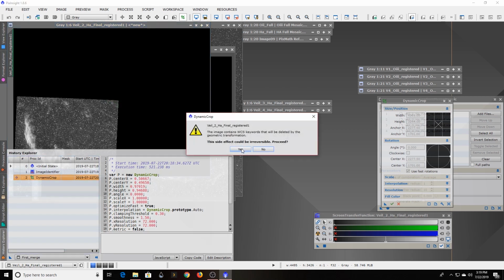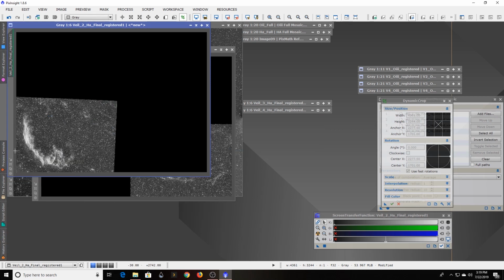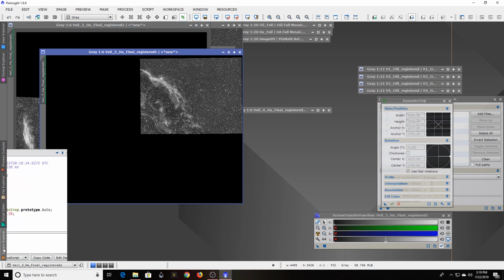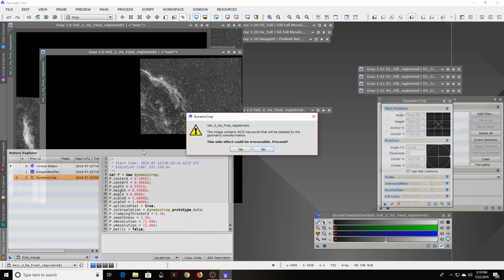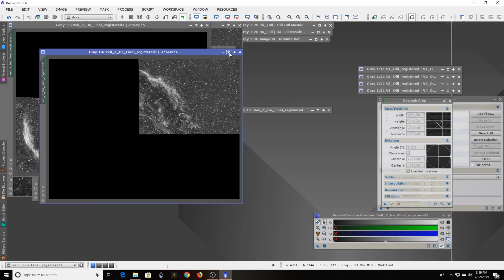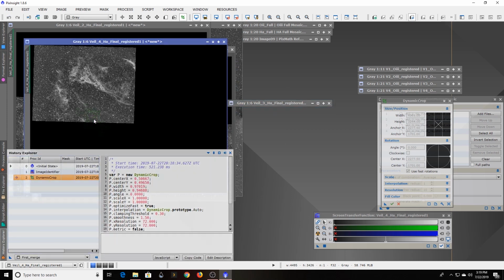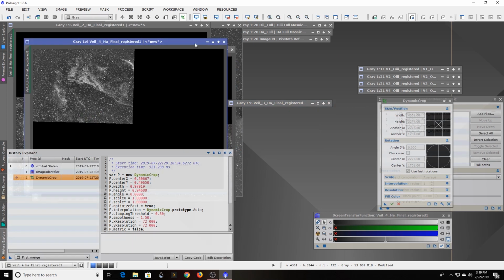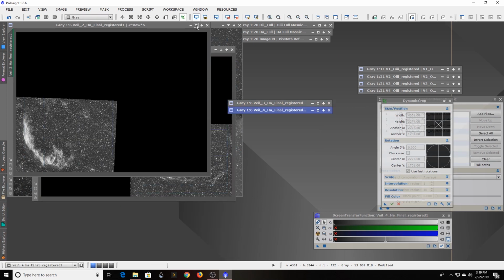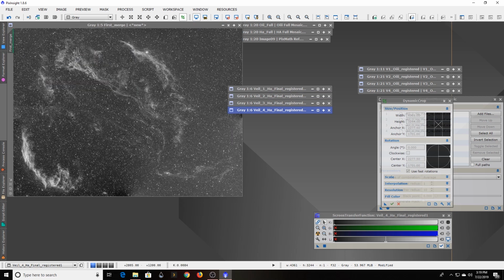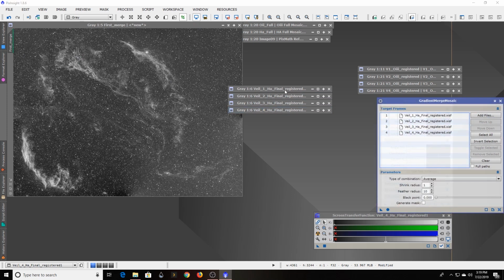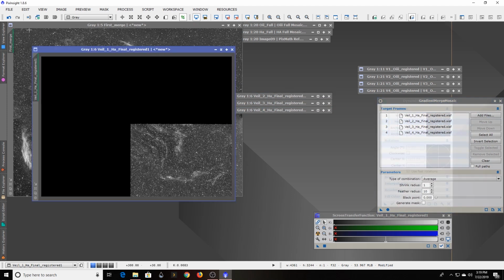So this one should be pretty obvious how that crop comes in. You can see all that black on the side got chopped off. Do it on that one. And then we'll do it on this one. So now that should give us a mosaic that has a little bit better kind of edging in here, and we'll see if it can take care of those things there. So on the gradient merge, remember, this only deals with files, so we need to go ahead and save these.